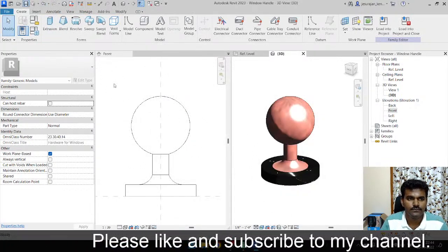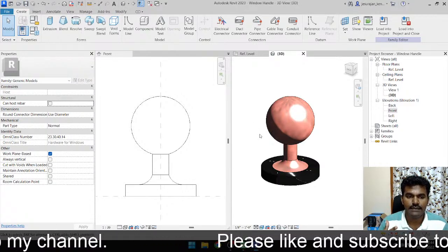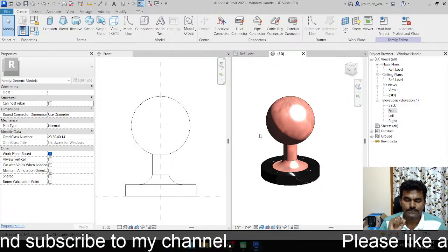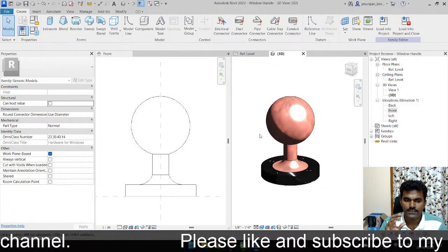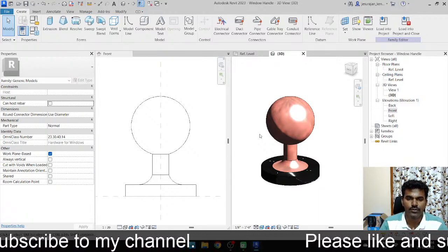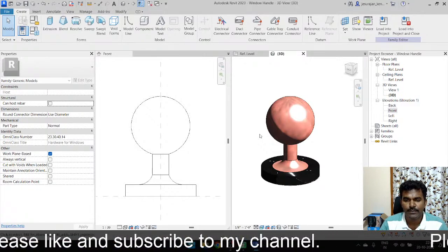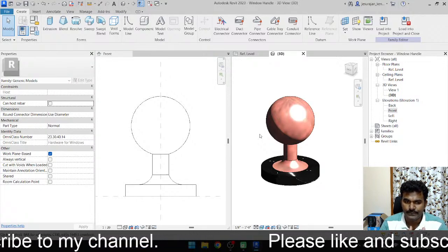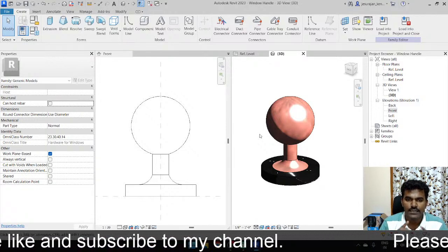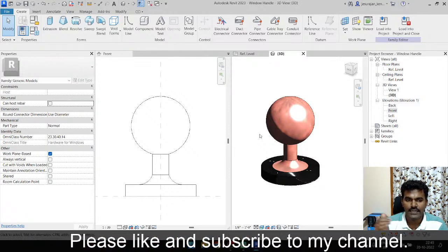Save this file. Here you should understand that we don't have to create every family as parametric. In case you're modeling a product, you can model it with the exact dimension, or with the exact ratio. You only need to create parametric when the type of product is available. So when you change the type, the same geometry will show the geometry of the type product.